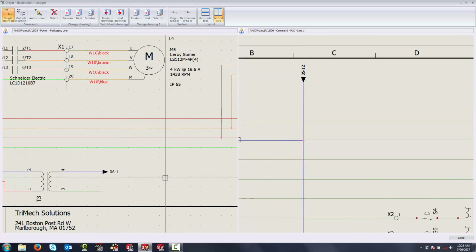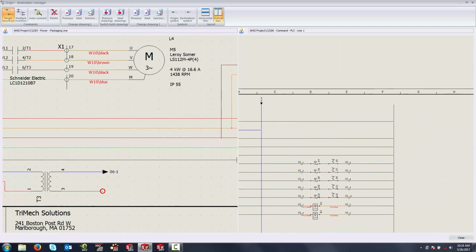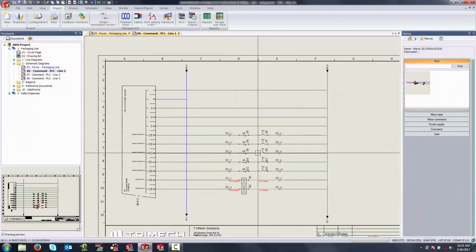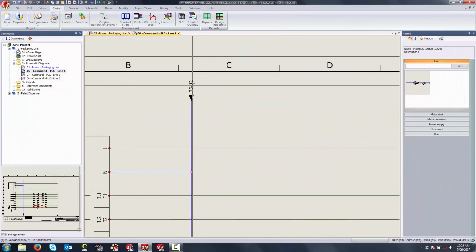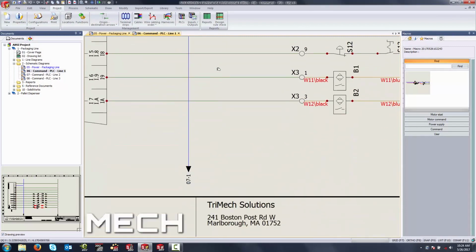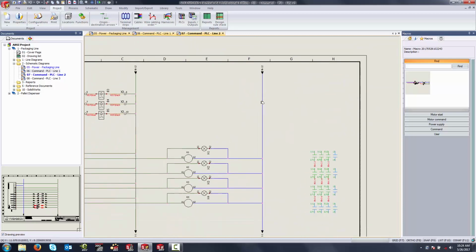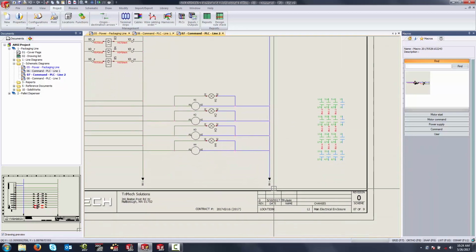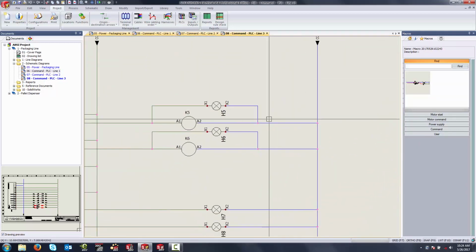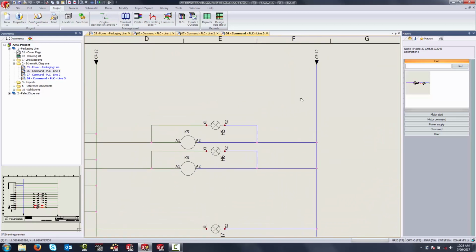And you can customize this to be whatever you'd like, but the process remains the same. So when I do this, not only is it going to connect the pages together, but it actually makes it very, very easy for me to navigate the drawing. If I go down here to these off-page references and double-click on them, what it lets me do is jump from page to page to see exactly where that connects. This is really useful when you're troubleshooting a schematic because it lets you jump to the relevant page without having to actually follow that reference and find what page it is. It's just a double-click away.